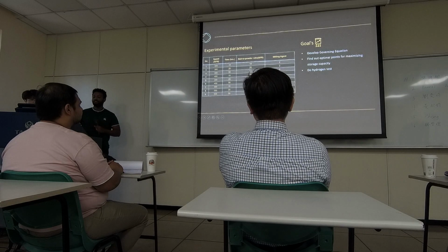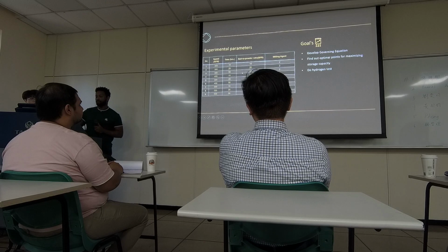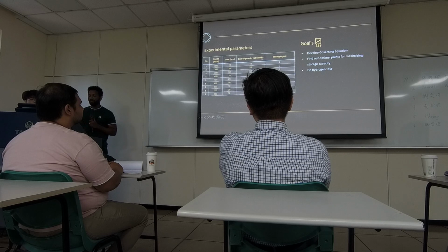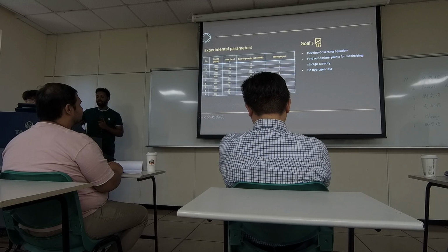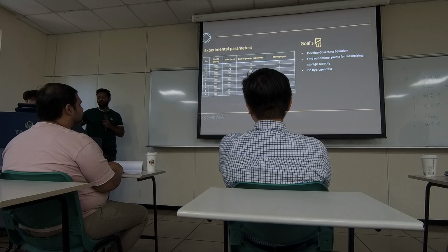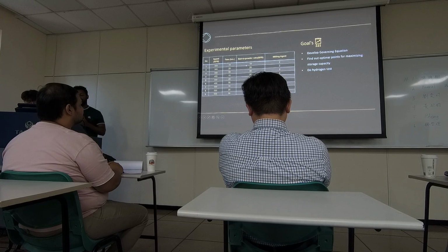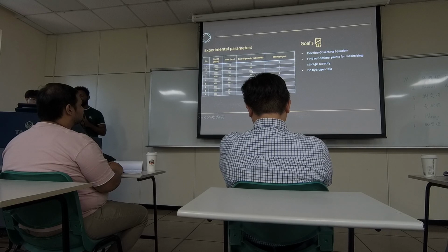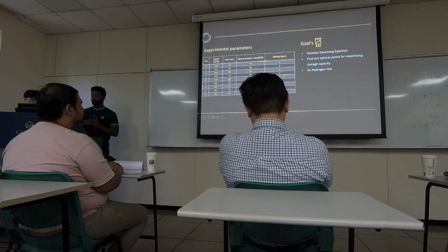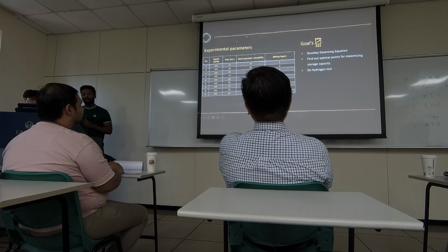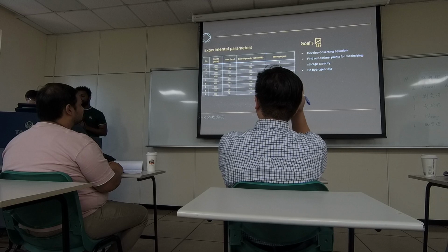So these are the experimental parameters used in this paper: speed, time, and ball to powder ratio. For speed, they have 3 levels: 300, 400, and 500 RPM are used. For time, 10 hour, 20 hour, 30 hour, and 50 hours of milling. And for ball to powder ratio, they used 10, 20, and 30. The fourth parameter is milling agent, but it is common for all the samples, so we ignore this parameter. So our parameters are these 3.